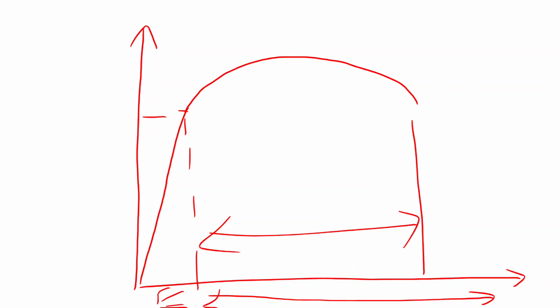So next we come to the curved upward region. After yielding, here it is the yield point, the material enters into the plastic region, and here deformation increases rapidly with a small increase in stress. This curve continues to rise until it reaches the highest point, which is here. This point is called UTS, which means ultimate tensile strength.